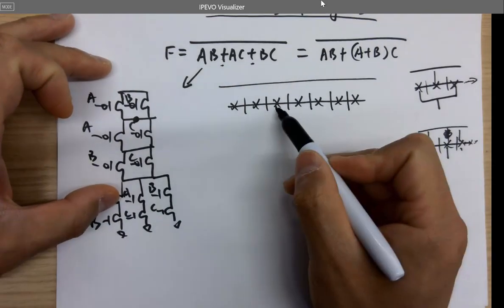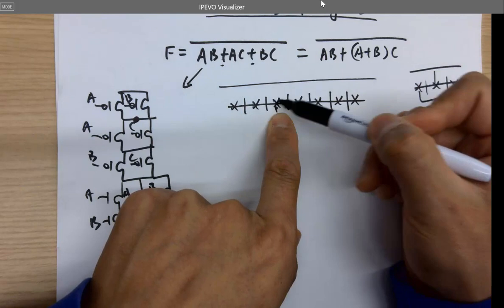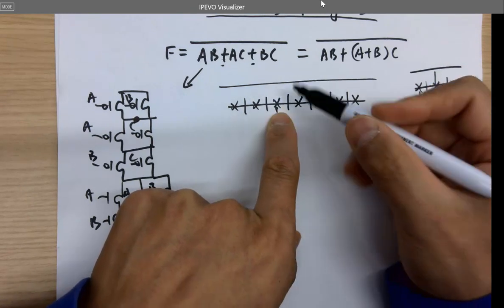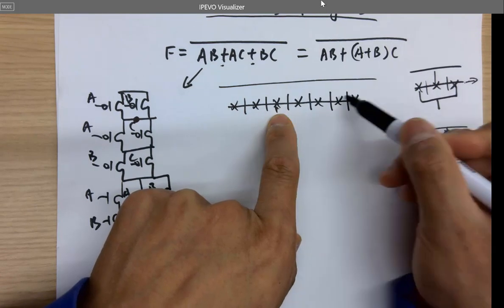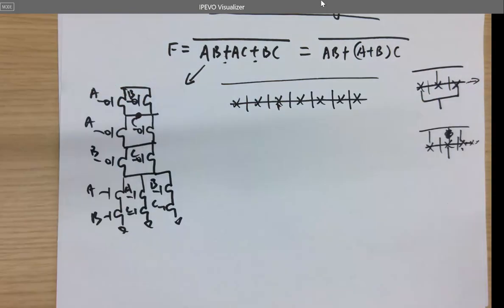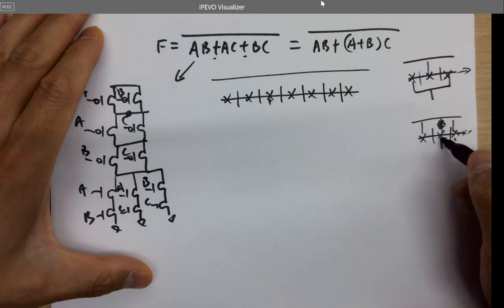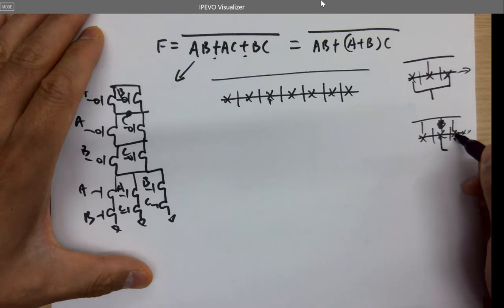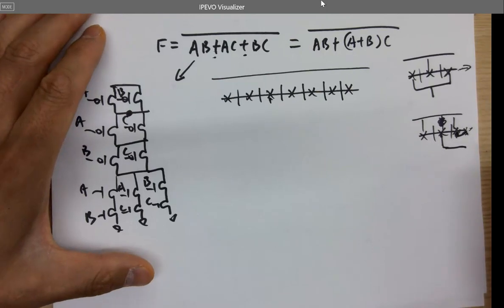So which means you have to use this one to connect them together. For example, these two transistors are in parallel, right? And this must be the output because in the one liner, it's already made the connection. You cannot change it. Did you get that? So if you do it this way, you are trying to use the middle node as the output. However, the node on the side is already connected to the next transistor. You know what I mean? Does that make sense?